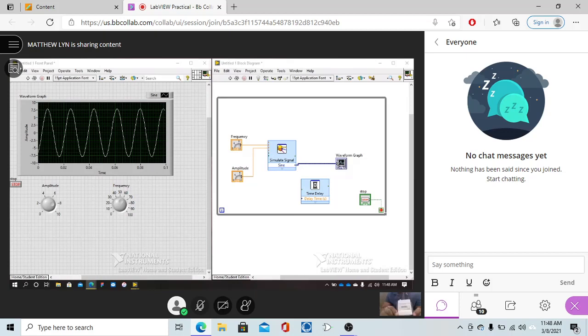Set up the hardware: connect the NI USB 6009 DAQ module to the PC using a USB cable. With the NI DAQmx driver installed on the PC, it automatically detects the USB DAQ module and brings up the following window.